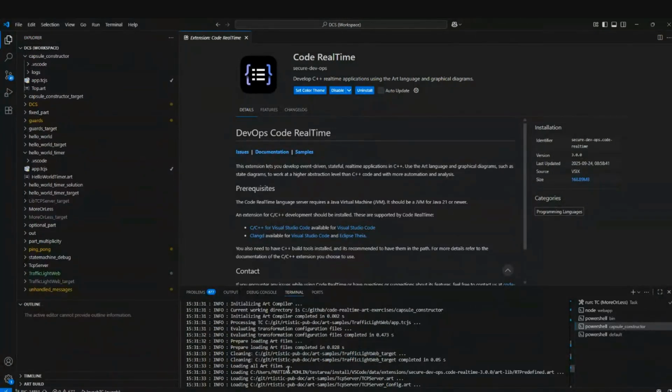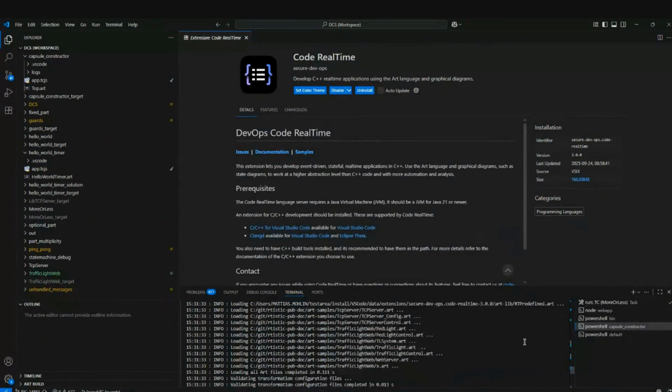And if you, for example, happen to have the executable running or some other process is blocking something in that target folder so that it cannot be deleted, then there will also be a message coming here and the build will stop, which is useful because otherwise it would anyway fail during linking phase when it cannot link the executable since it's already running. So that is the clean build feature.